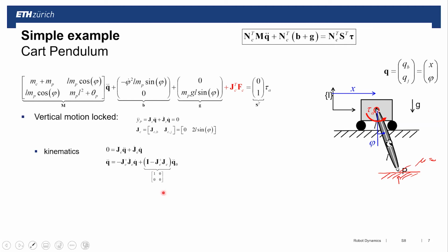What I told you last time is that the NC can be directly seen here, which is a 1 and a 0, because if I multiply that one with 1 and I add this one times 0, I get a 0. Now you see also the difference here. So this has only a second column vector, which is 0. So the span of this, what the space that it spans, is really only a one-dimensional system, although we have a two-dimensional matrix. So the rank of it is 1. That means the constraint allows us to move in one single direction if we have that constraint active.